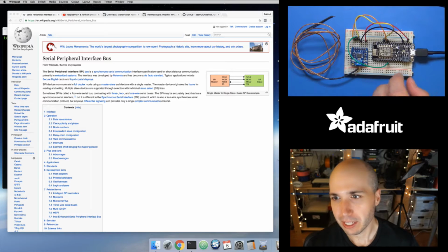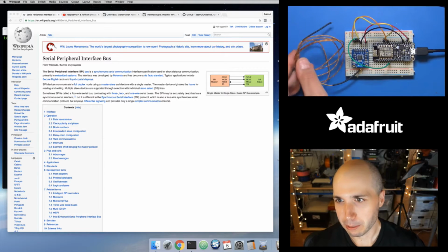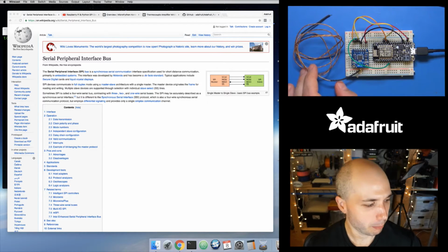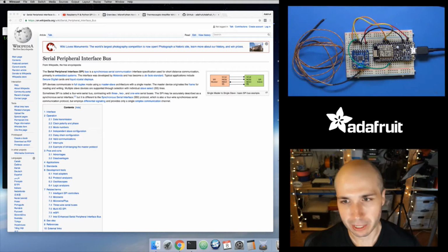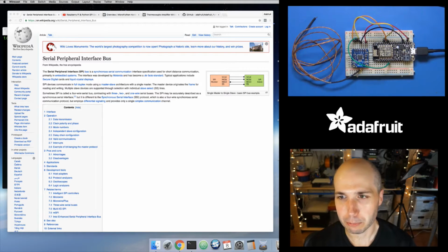This is a little more advanced. Connected to the board is the MAX31855 thermocouple sensor. Then this little long metal thing here is actually a thermocouple, just a basic K-type thermocouple. On the tip right here, it's actually a couple pieces of metal. The way it works, I believe, is the voltage will change slightly, and then the amplifier has to amplify it a lot so that you can tell there's a difference. Based on the temperature change, it changes the values it reads out of the thermocouple.